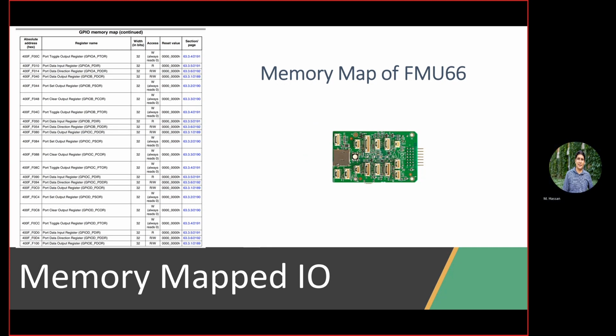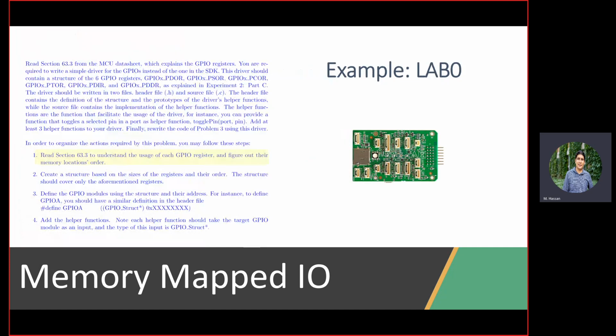Good. I will assume also you have done something very similar for the TI board you have done in the 2DX, right? Because there is no way you can really write to an actual input-output device without knowing it, unless you have been using already given libraries for you to deal with the drivers, right? Which we'll try to avoid as much as we can in that lab to give you a chance to interact with the real world. Here I'm showing you the example we have done in Lab 0. You needed to read the data sheet basically to come up with the uses of each GPIO register and figure out what the memory location is to be able to deal with them.